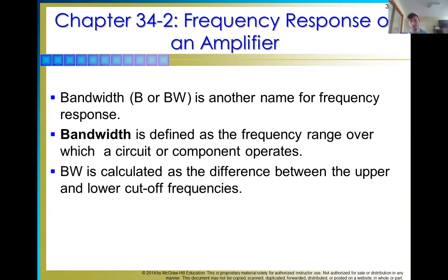Anyway, as we look through it and get used to hearing bandwidth, it's like, bandwidth, what does that mean? And that is exactly it. Your bandwidth is the lower to the upper allowable frequencies of that particular circuit. And when you look further, you'll start seeing tables listed out, like with the AM allowable. AM has a specific frequency range.